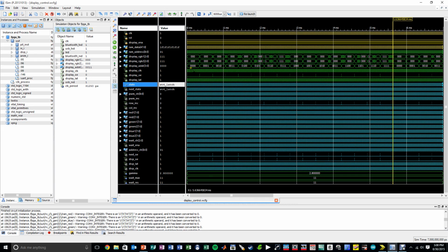And you can see here the display address slowly increasing from 0 all the way to 15, meaning, remember, we are driving the top and bottom portion of the LED matrix in parallel. Once the address counter reaches 15, we have written 32 lines in the matrix, and the frame is complete. And you can see writing one full frame takes roughly 5.64 milliseconds. So in 1 second we are able to write close to 200 frames per second.